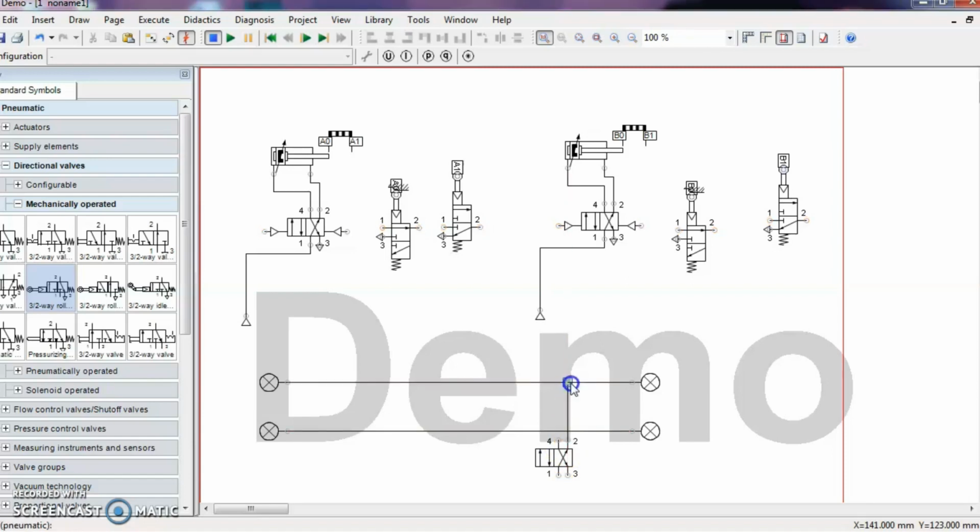Now we see the connections. First from the cascade valve, draw a line to pipe 1. From pipe 1 we have to operate cylinder A, so join from pipe 1 to the left side of the DCV. Then cylinder A extends, so it actuates the limit switch. From the limit switch we go for the next operation. Our next operation is A plus, A extends, then B.